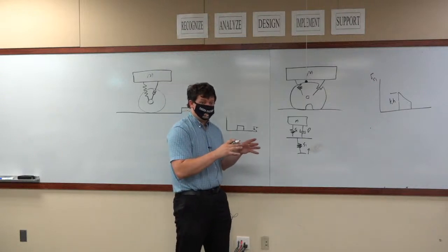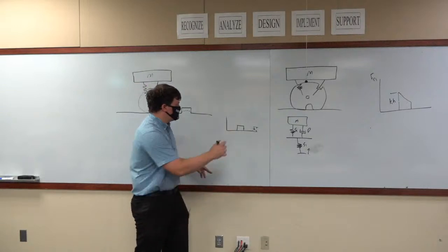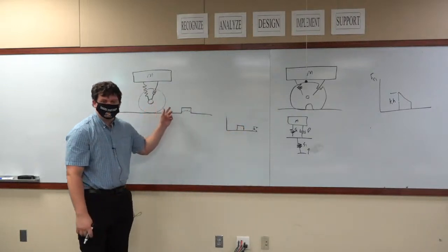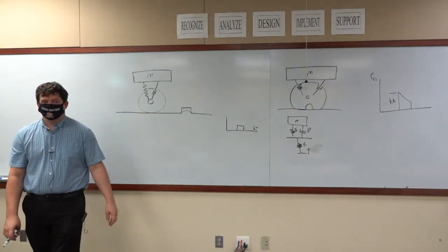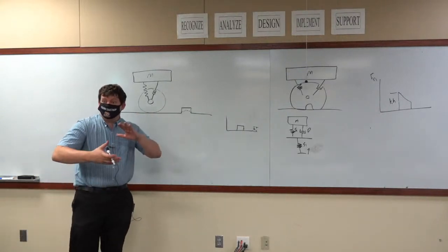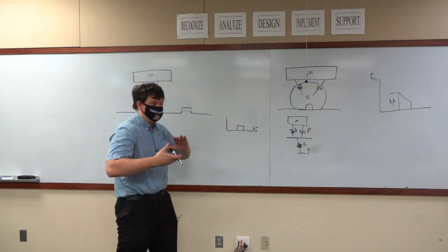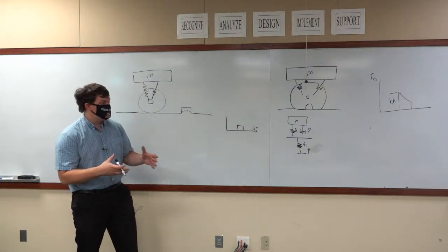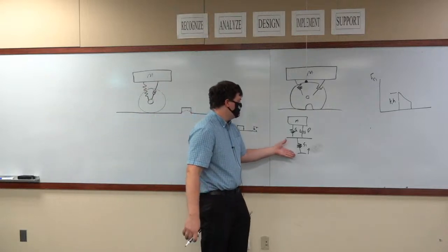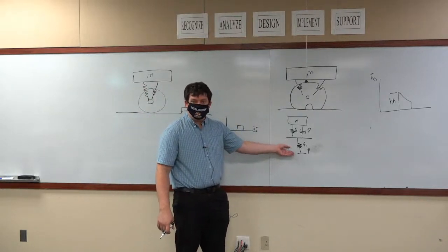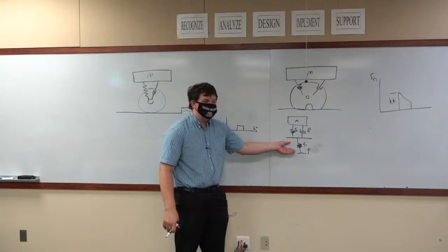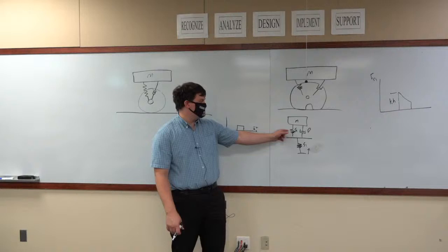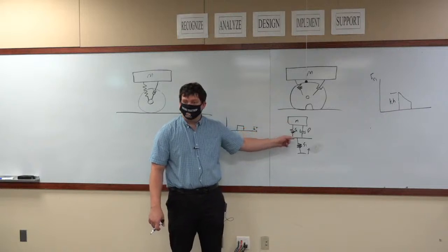And in order for it to return to its shape, as it is traveling over this, what has to happen to the suspension? The suspension itself is compressing. So the tire is returning to its natural shape by equalizing some of the force that's here. At the very beginning, all of the force of hitting that bump is stored in the tire. Every bit of it. None of it is transmitted here.